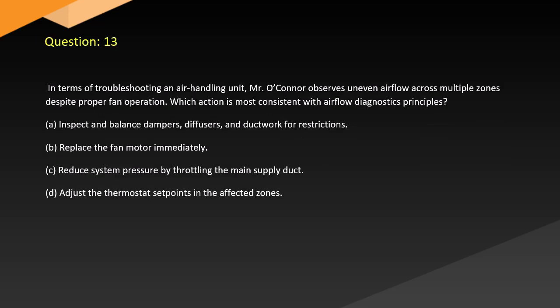Question 13. In terms of troubleshooting an air handling unit, Mr. O'Connor observes uneven airflow across multiple zones despite proper fan operation. Which action is most consistent with airflow diagnostics principles? A. Inspect and balance dampers, diffusers, and ductwork for restrictions. B. Replace the fan motor immediately. C. Reduce system pressure by throttling the main supply duct. D. Adjust the thermostat set points in the affected zones.